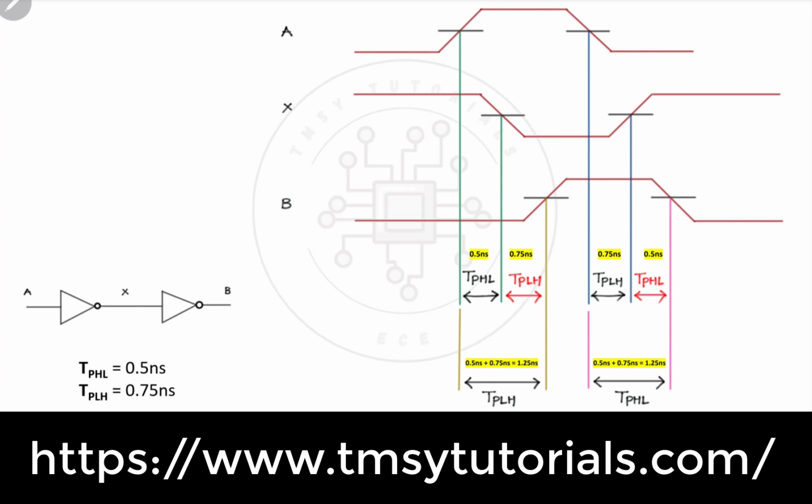So let us analyze these cases. First I am checking for A and X. Simply draw a vertical line here, and this is another vertical line for X, which I am taking at the 50% point. If you observe here, X is changing from high to low. So we need to write this as TP-HL. So this is TP-HL.